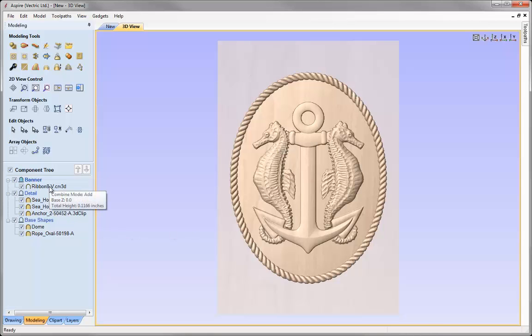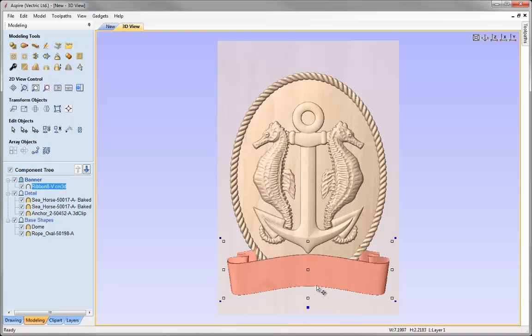And this is where it becomes very important in the 3D view that when I select that I can see the green silhouette there, and now what I can do is click on that again in order to be able to select that, hold the shift key down and then just drag that vertically down. The shift just is going to keep that vertical, and now that it comes to an area where it starts to be more prominent, I'm going to see it sticking above apart from on the bits of the rope there. Again I'm going to hold shift down so that I can scale that up around the center there, and we can just make that whatever size we want.